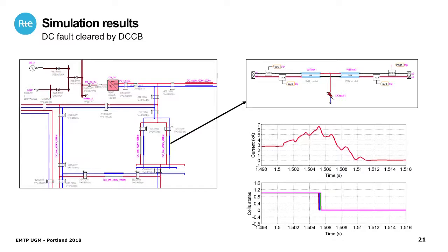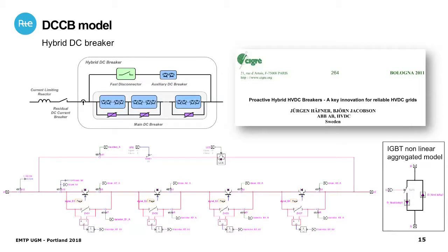Yeah, I have to check again if they are synchronized or not. You're talking about, just a second, which part? Okay, this one you're talking about? No, the left, yes. That's the mechanical switch, which takes at least 2 milliseconds. So once you commutate the current from the auxiliary branch to the main branch, it conducts for another 2 milliseconds, just waiting for the contacts to get fully in the open state, and then you can open the main branch.